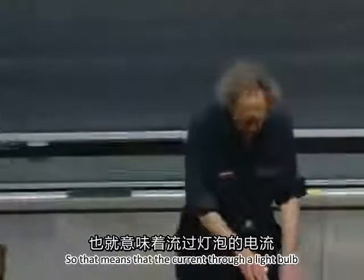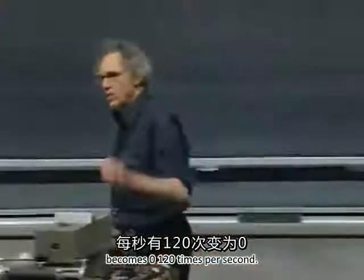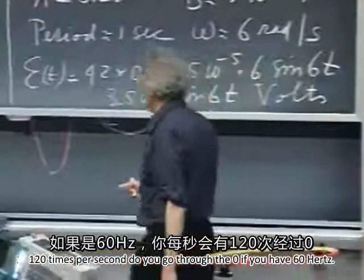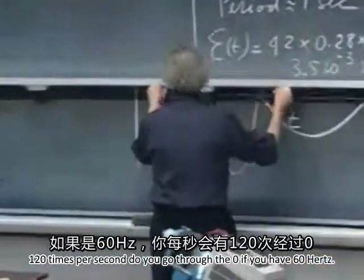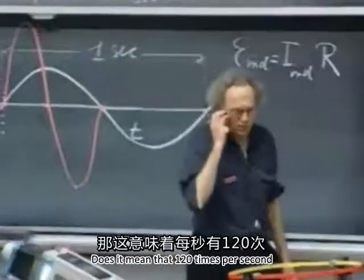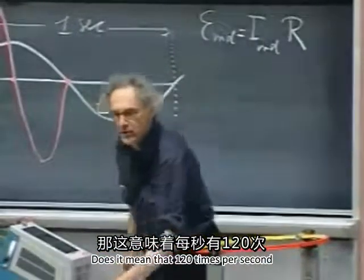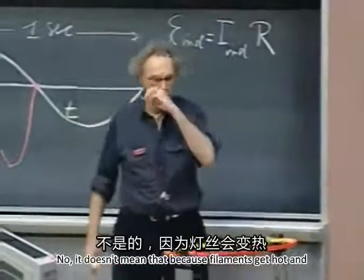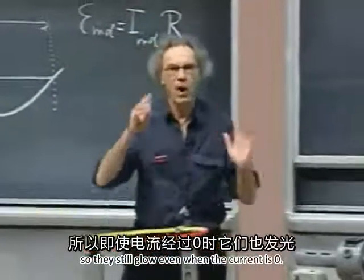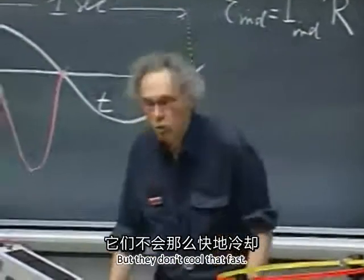So that means that the current through a light bulb goes to 0 120 times per second if you have 60 hertz. Does it mean that 120 times per second there is no light from the light bulb? No, that doesn't mean that, because filaments get hot, and so they still glow even when the current is 0, but they don't cool that fast.